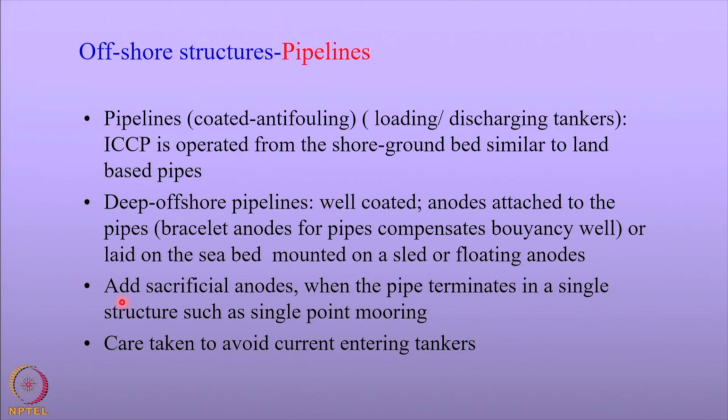Let us look at the offshore structures now in specific. Let us take the pipelines. The pipelines are coated with the anti-fouling coatings. The offshore structures have a lot of marine growths, and in order to avoid the marine growths, anti-fouling coatings are given.